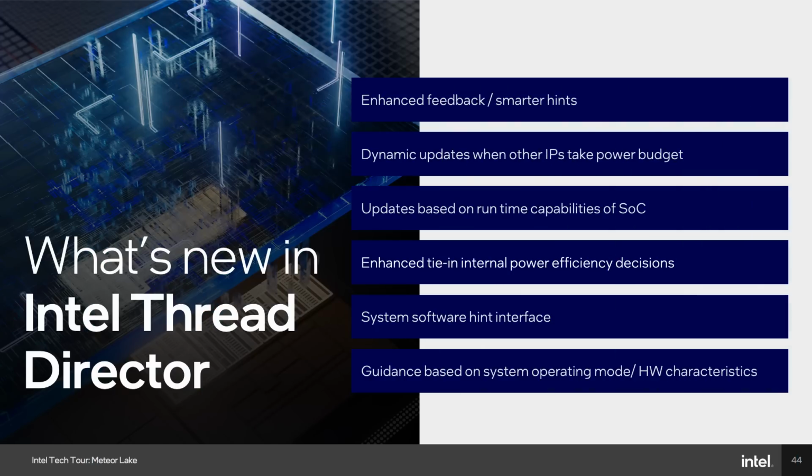All this work is now tied back to the software, so Intel Thread Director can have the ability to schedule the right thread, the right workload, on the right core at the right time, and it allows us to turn the other tiles off. And so that software, and tying it back to the overall system software, has been very important. And the Thread Director allows us to give hints to the OS to actually move the threads back and forth between the different cores and do the optimization points that are there.